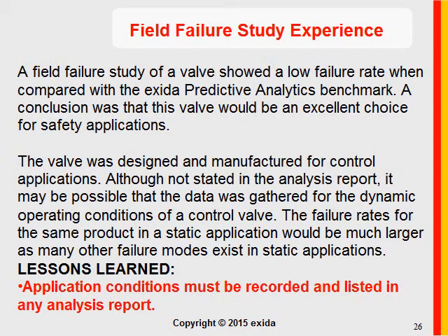Now you might be asking, whoa, what about when I use a solenoid valve with a control valve? Well, if the control valve is moving and it is being used in a dynamic application, then a dynamic FMEDA would indeed generate a lower failure rate.